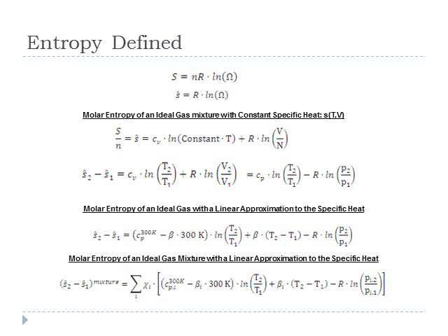So you can correct the equation above, and it has an effect. We're using C sub P at 300 kelvins, and you still have the logarithm of T2 over T1, but you've now added this linear term, beta times T2 minus T1. And you still have the minus R times the log of P2 over P1.